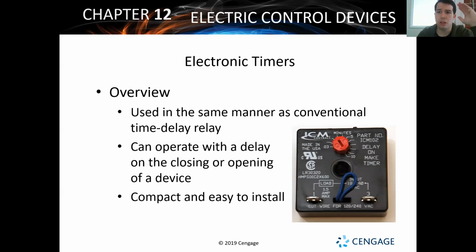Now, you all learn about exactly how a heat pump operates, but basically it takes the refrigeration cycle, the air conditioning cycle, compressor, condenser, expansion device, evaporator, back to the compressor, and it's going to reverse it. Now, to reverse it, that takes a lot. One of the things you have to make sure of is that the pressure is not uneven on either side of the compressor when it starts up.